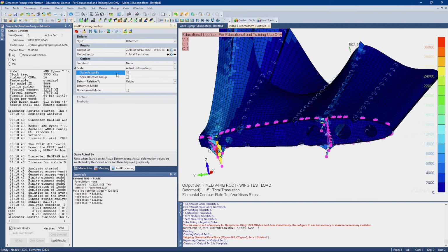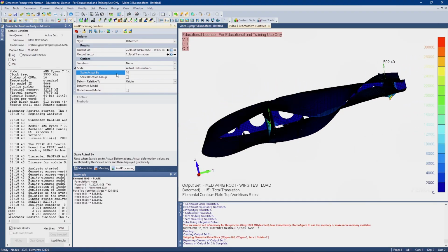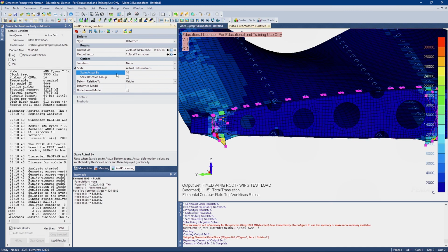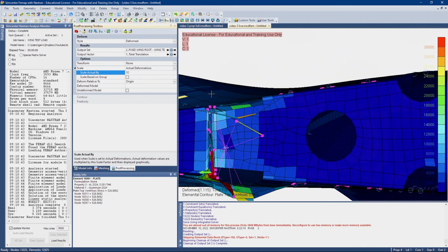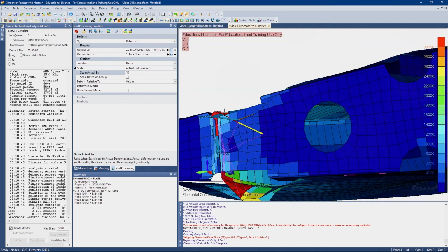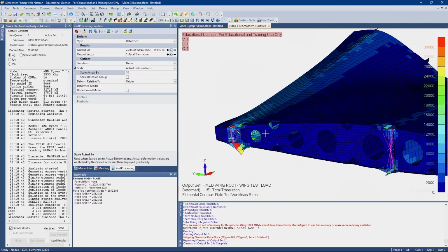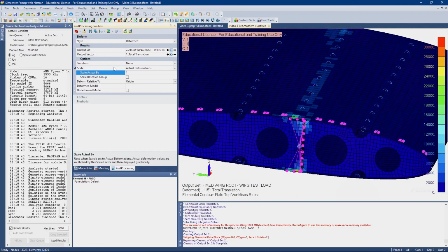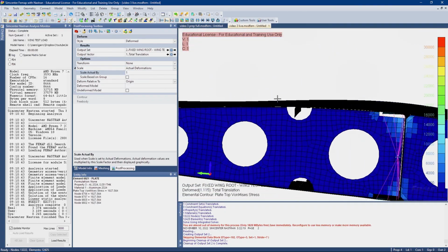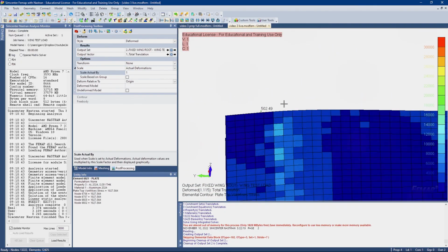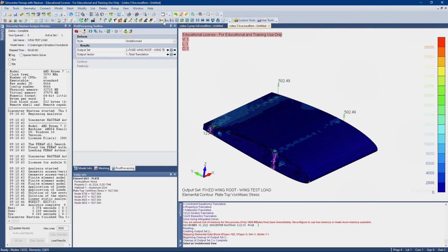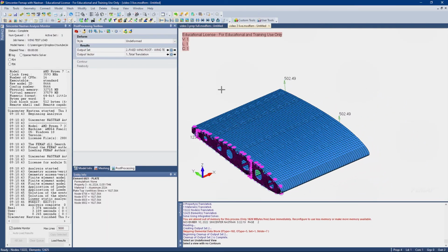Turn on maybe a little bit too much. Here we go. Here's 30 times displacement. What's going on here? Okay, I think that's just the bending of the C channel. 10x looks a little unrealistic, but again, if we put it back to 1x, it's fine. And everything looks good. So we are ready to pattern this mesh.